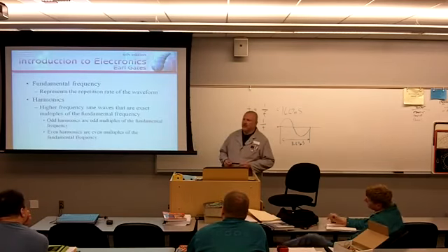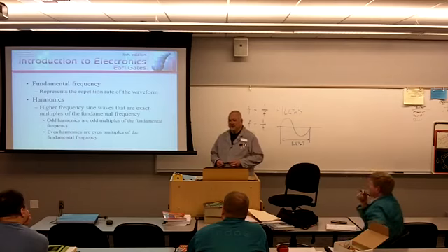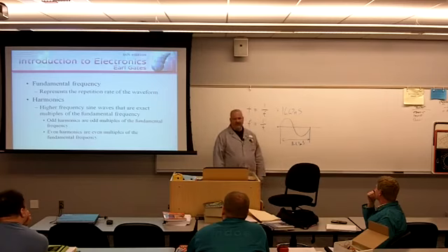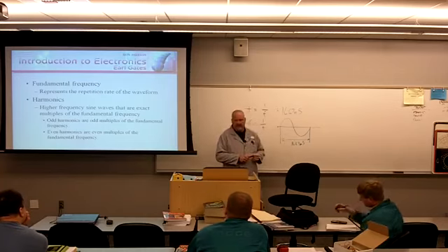Fundamental frequency is a frequency that represents the repetition rate of the waveform. This here would be the fundamental frequency for a 60 hertz waveform. This is the period, right? 16.67 milliseconds. Reciprocal of that gives me frequency, 60 hertz, fundamental frequency.